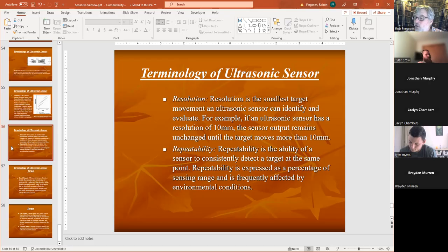And especially in ultrasonic sensors, it's affected by your environmental conditions. If you have foam on top of your liquid that you're measuring in your tank, guess what that foam is going to do to your ultrasonic signal? It's going to mess with it. If you have vapors on top of your tank, if you have any number of things that can occur, powder, dust, you could have a tank filled with gravel where the tank has basically a big funnel.